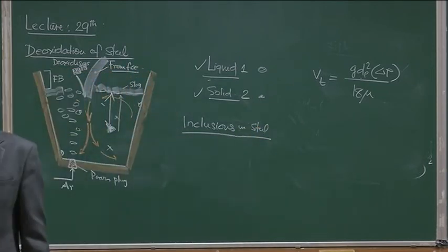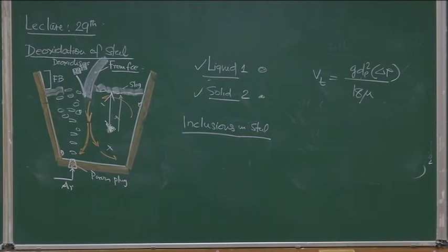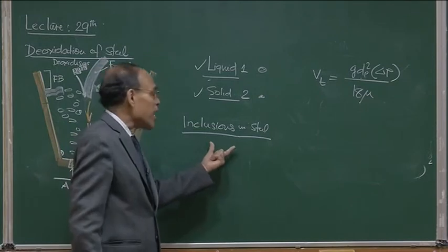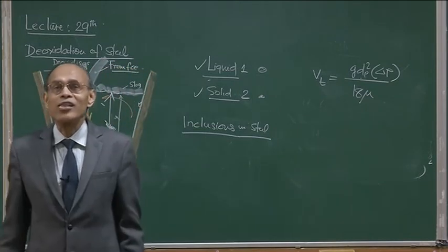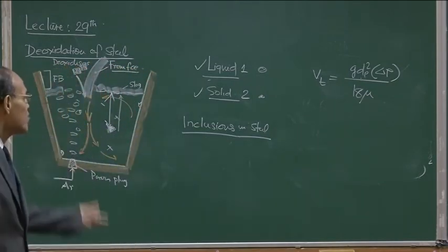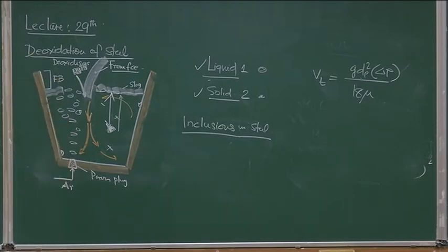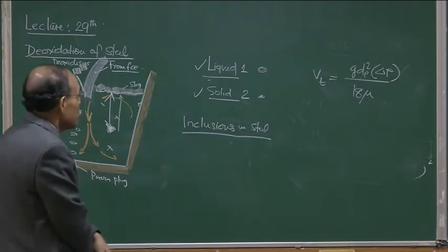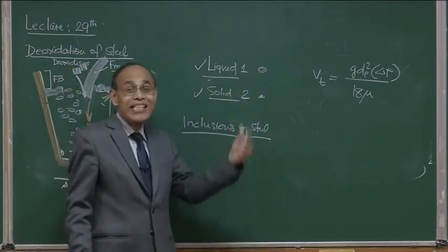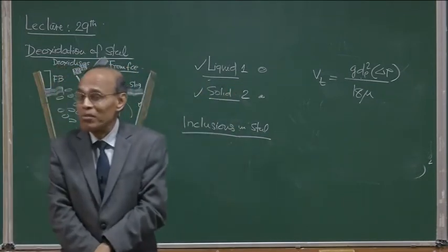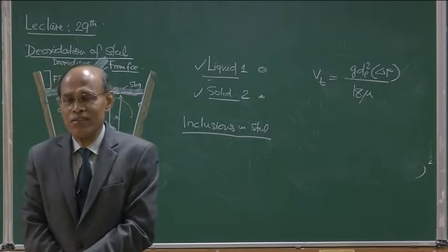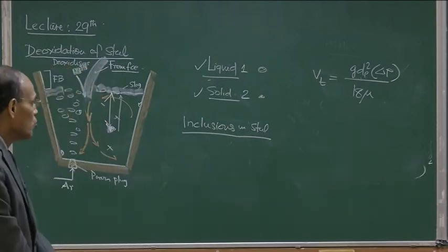If steel is free from inclusions, we say steel is clean. So cleanliness is a term which gives us an impression of how successful you have been to eliminate the deoxidation product from steel. So therefore, we will say that when manganese silicate is going to form, there is a liquid deoxidation product. Rarely we will find manganese silicate deoxidation products.